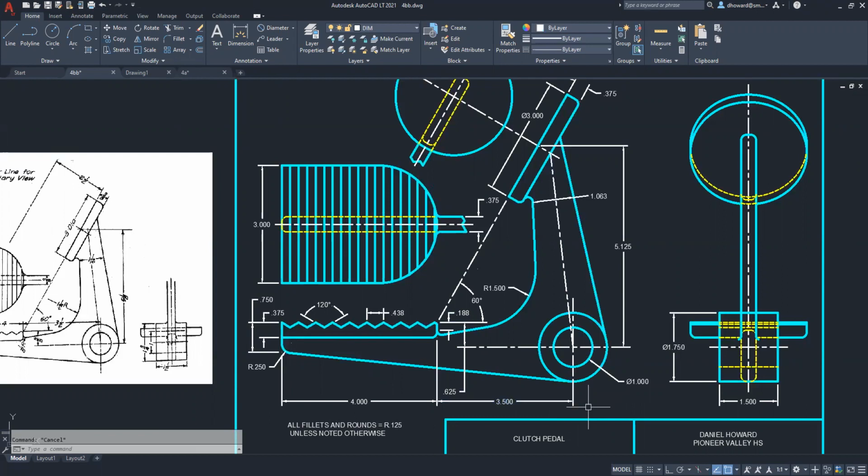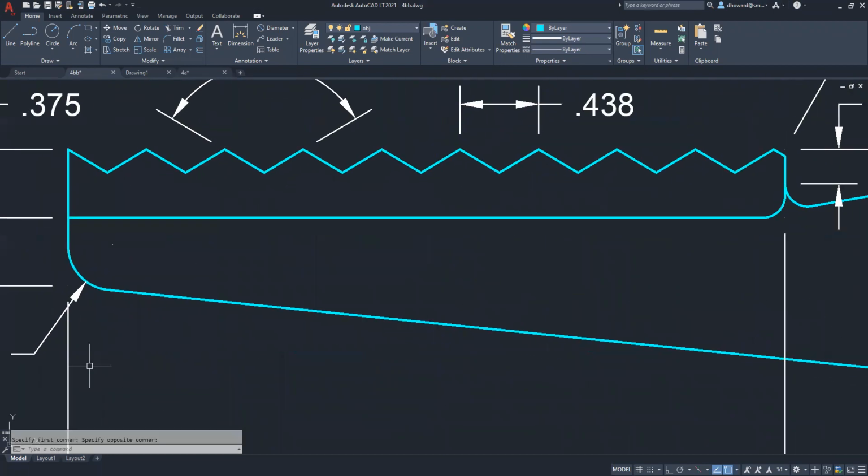And on the next side, with the 4-inch dimension, we're careful not to go into the arcs. I know I always say this, I will reiterate it here, that this point of origin for the extension line is not making contact with the object, okay? But that is not what we want to do.